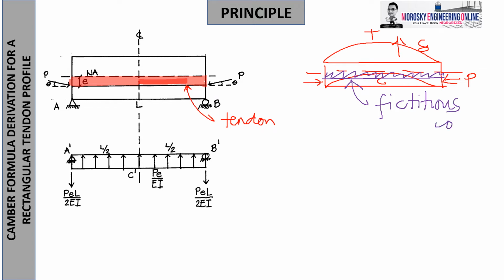It is a fictitious load because it is not a real load, but it is the product of the interaction between the eccentricity E and the compression force P. Those two, it turns out, produce a moment. Remember, when there is bending, flexure, a moment is created, and here we understand that moment equals P times E, the region shaded by that violet portion.